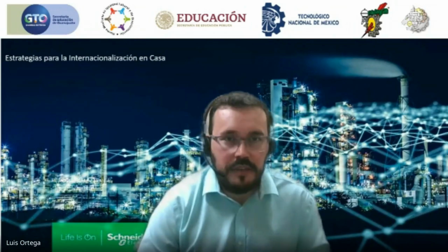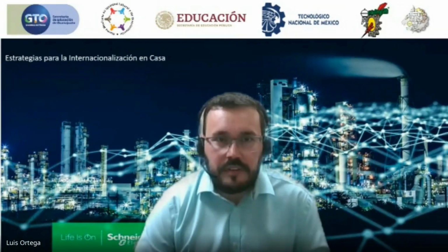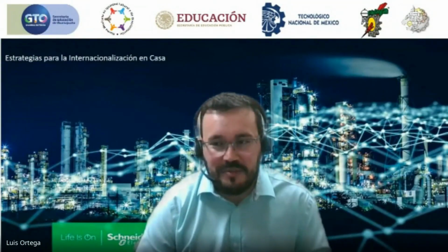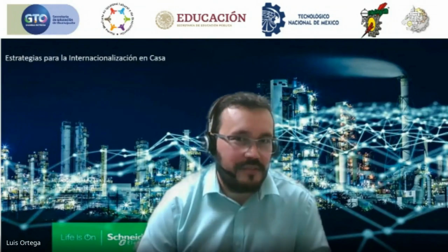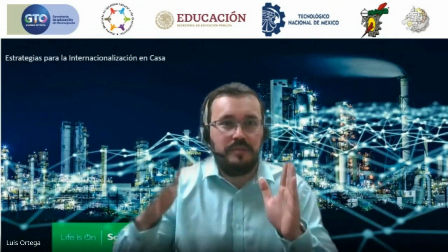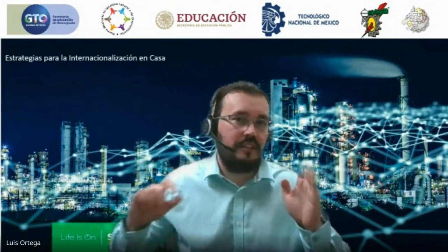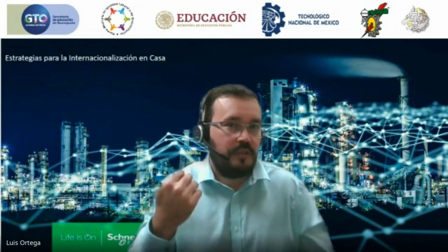The integration will be a little different now than before. Ten years ago, when I started in the industry, the smart factory was just a concept. It doesn't exist yet. When I was working, the PLCs were a bunch of cables, a lot of input and output cards, about three racks in the PLC just to handle all of those input cards. I'll show you how the rack is now in the PLC. It's just one input card, one output card. The rest of them is just Ethernet.